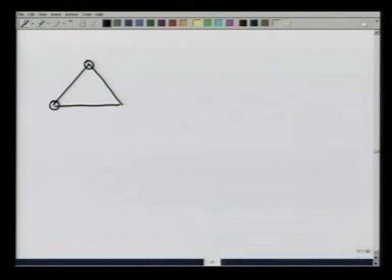So, let us see now, given a basic truss like this which I just solved for, how can I make a bigger truss? Let us see, if I want to extend this further, I put a member here and give a joint here. This joint now has 3 members that can provide equilibrium. Then this point, suppose I don't want to provide a support here, I have to provide one more member, and I could provide a fixed support here, a fixed support here. That is one possible truss.